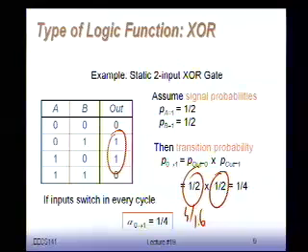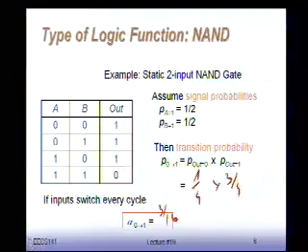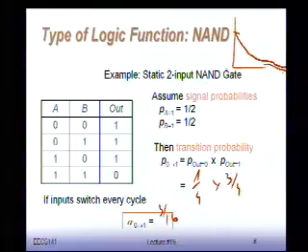Now, actually, the downs are definitely right, because if you think about it, let's go back to this previous picture. Take a 2-input NAND gate; if I do a 4-input NAND gate, everything is going to be ones, with one single 0. So the probability of having a 0 is getting very small. And if you look at the product, we'll see that asymptotically the probability of transition, which starts at 3/16, as you increase the fan-in, is going to go to 0. Big NAND gates or big NOR gates don't switch very often.